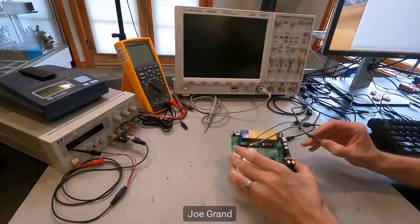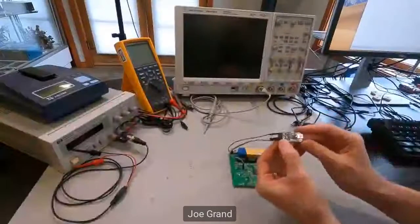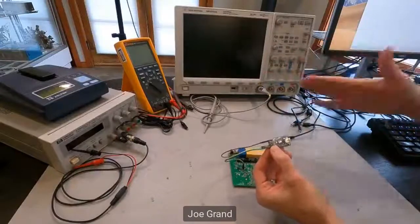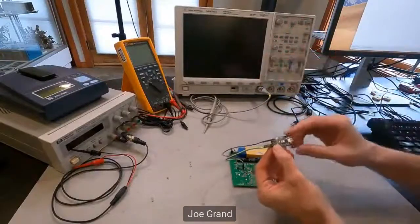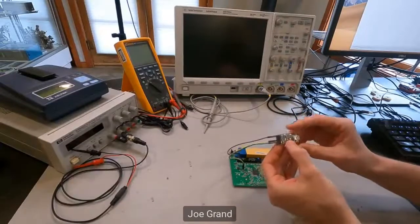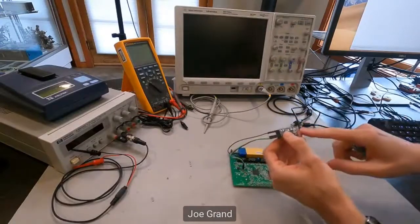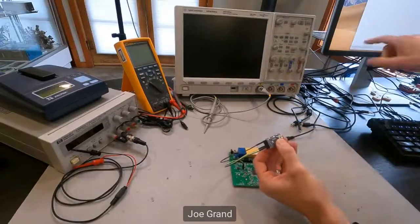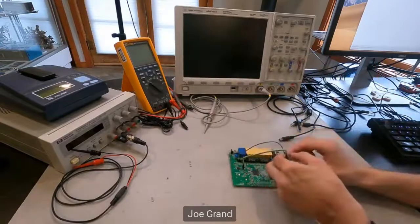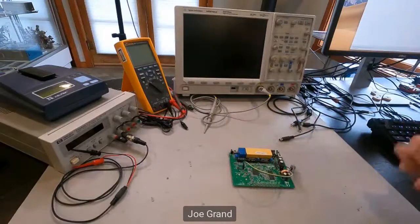All right, so I have this board here, and I already have the UART interface identified. What I'm using to convert the UART data that we were seeing, say, on the oscilloscope, which is just passing by really fast and kind of hard for us to read, into something more useful, is a USB to serial adapter. This one is called the FTDI friend. This is going to take in the UART data from the system, convert it to a virtual COM port, so we can plug that into our computer. That's going to show up on our computer screen. We can have a terminal program running. And then instead of just seeing data come across the screen really fast, we'll see it as it was intended to be printed on the screen.